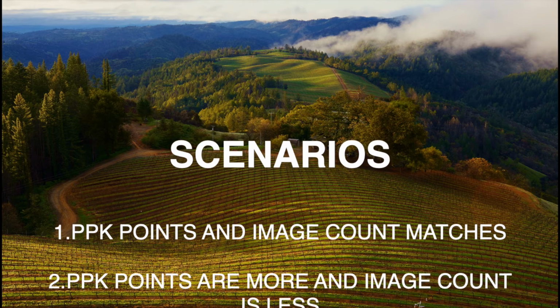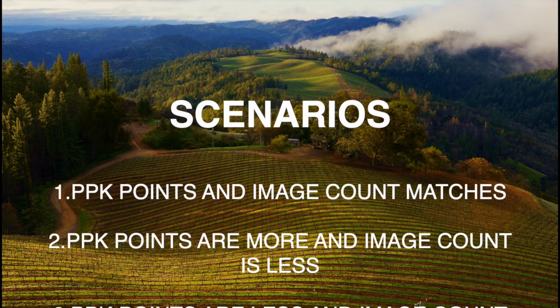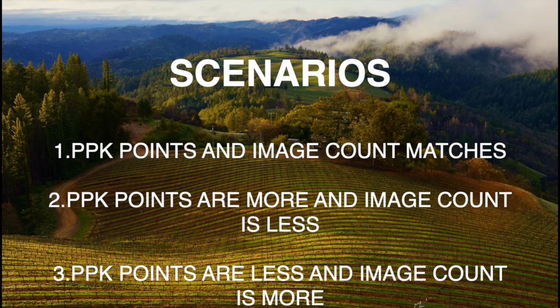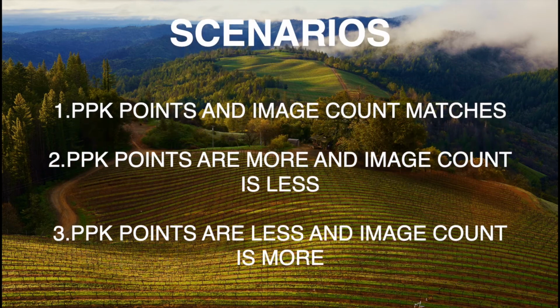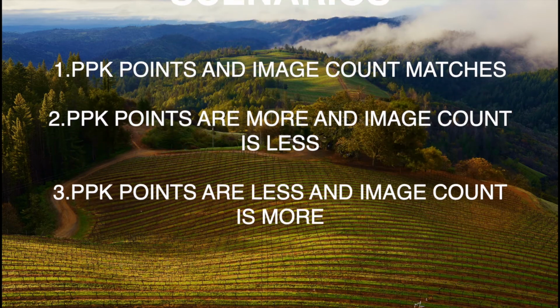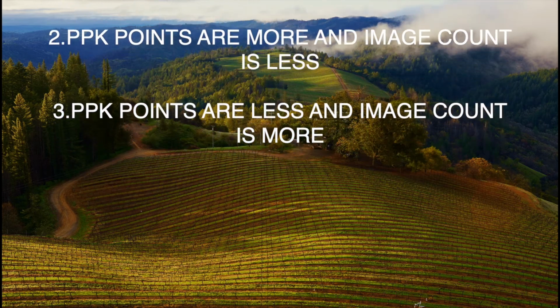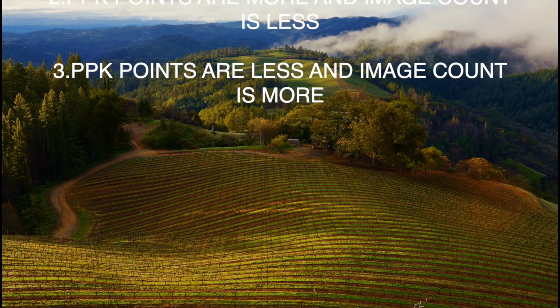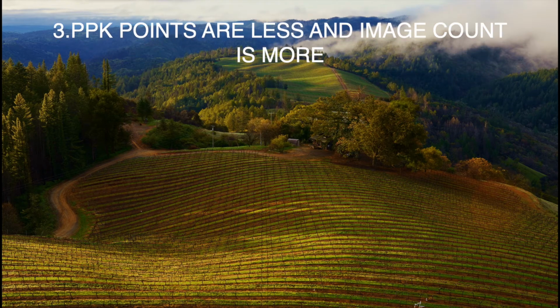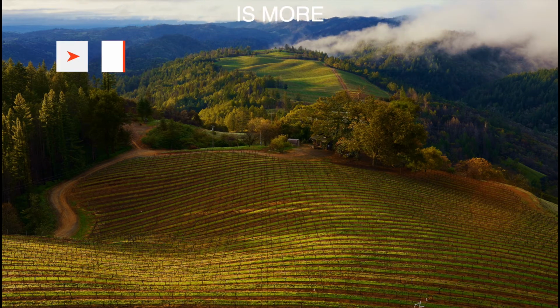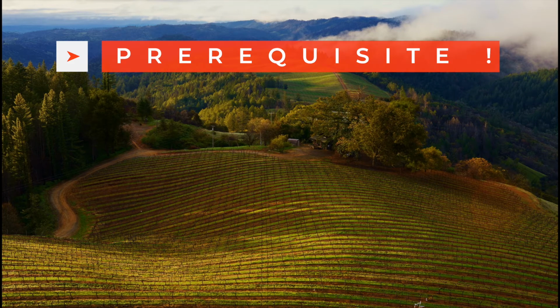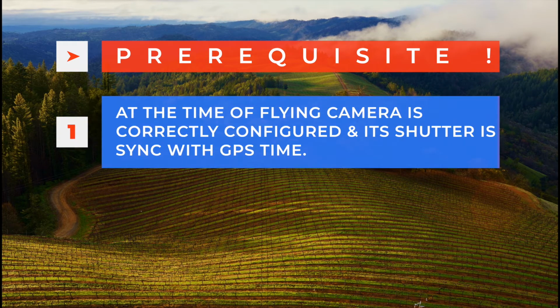We may come up with two more scenarios where either PPK or image count is mismatched, and in coming videos we will take up those two cases as well. That's a bit tricky, but for now we will proceed with a scenario where image count and PPK points are matched. Before we start, ensure at the time of flying that your drone and camera are correctly configured.